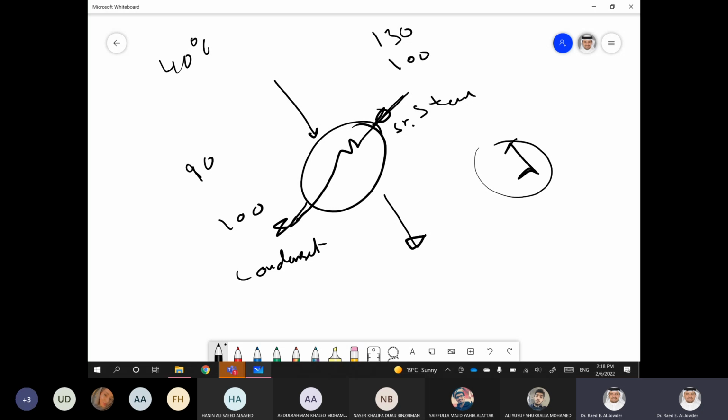This is number one. Number two, superheated steam is categorized as a poor energy conductor. It acts like air. It's more of an insulator rather than an energy conductor. So to achieve the same amount of heat transfer, you would need a higher flow rate and higher energy levels. So it's not efficient to use superheated steam.